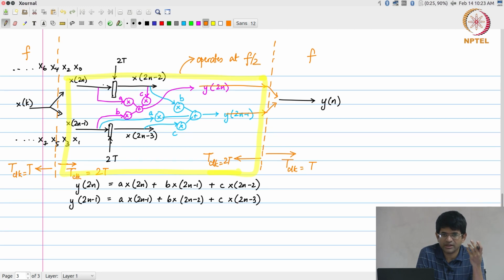What is the connection between the operating voltage and the propagation delay through a circuit? In general, if I increase the operating voltage, keeping the technology otherwise the same, would I expect to see an increase or decrease in propagation delay? I should see a decrease, right. In other words, the circuit can switch faster, right.